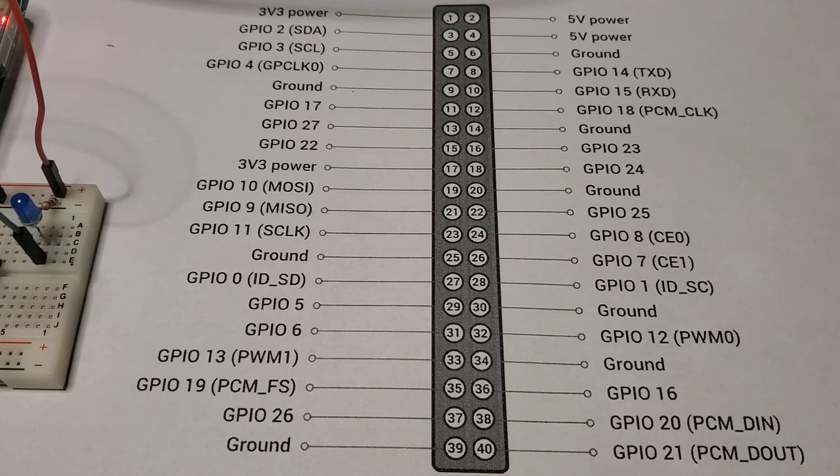So just going through some of the capabilities, all the GPIO pins on the Pi are 3.3 volt tolerant. And unlike the STM microcontroller, they are not 5 volt tolerant, so you definitely want to keep 5 volts away from any of the input pins here. The processor itself is an ARM A72 based processor, so it's similar to the STMs in that they're both ARM architecture, but the Pi 4 is based on a BCM2711, and I'll include a datasheet for that microcontroller. Obviously the datasheet contains all the information on how you go about programming the peripherals, which we'll get to shortly.